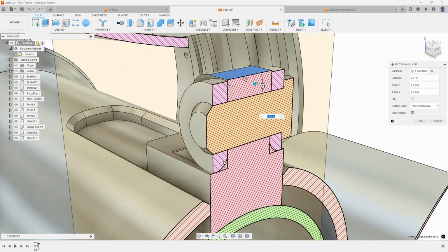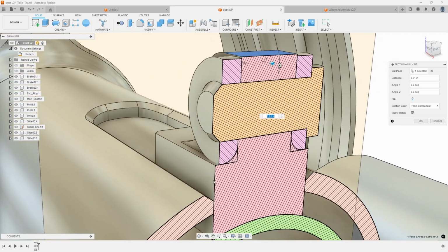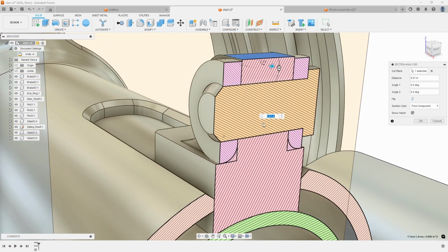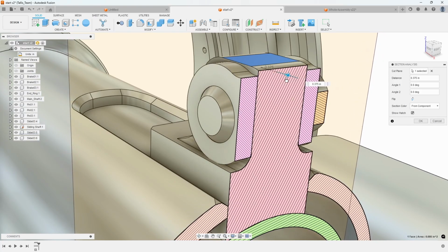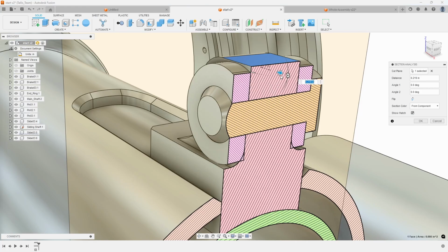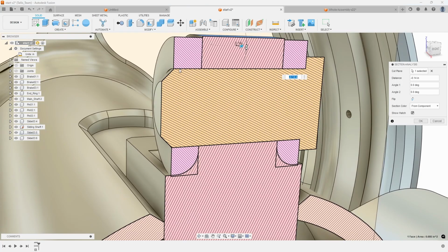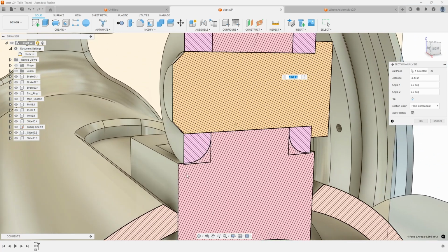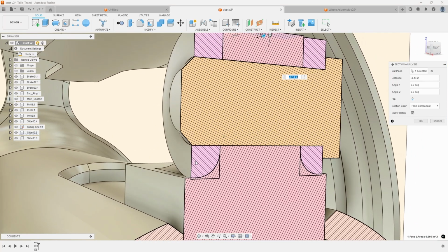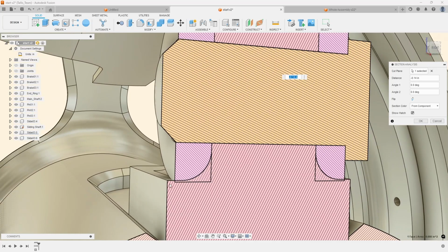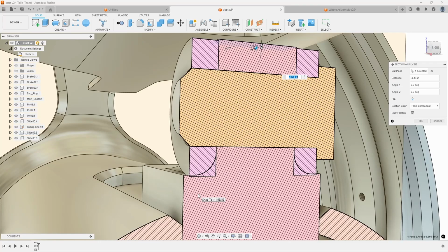And here's another very visual representation of this control arm clashing with that mount right there. So we can kind of visually see as we slice into there where that's starting to clash. So it's a very visual picture. And we can see everything else looks really good, like this pin going through and all that kind of stuff. We can also even see that this control arm is actually too tall. Even if we were to remove the fillet, it looks like it still wouldn't work. So we have a couple changes we need to make.